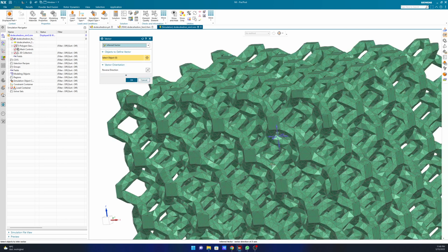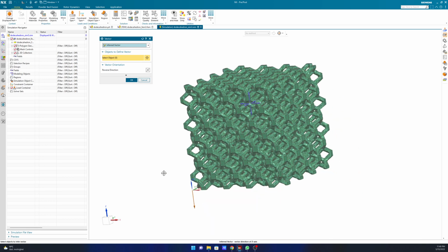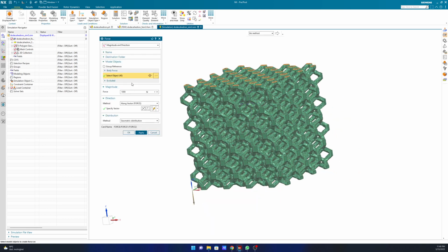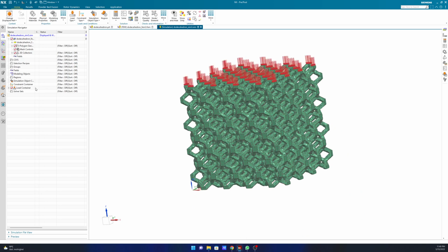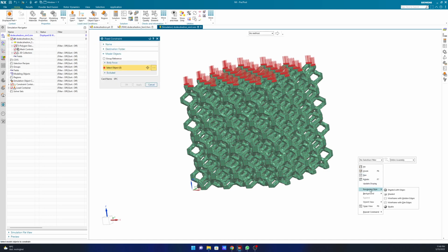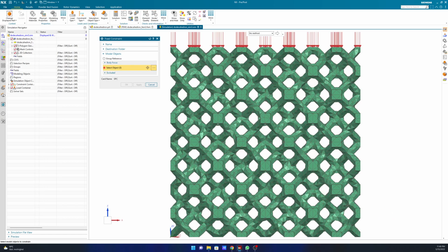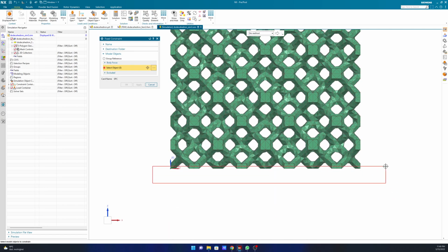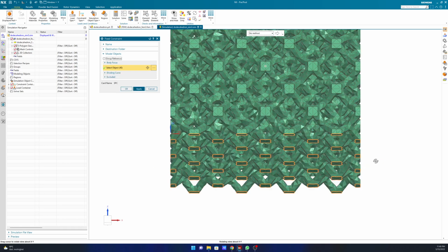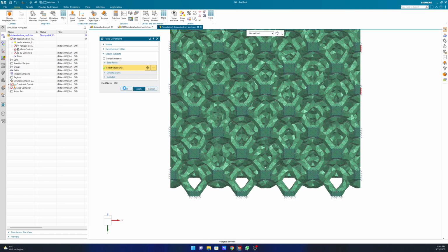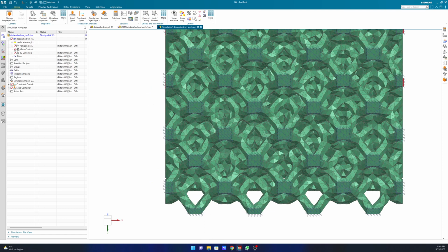Let's select that. Yep, it did. We have the direction, we have the load. We just click apply. There's a load. Then we'll have to put some constraints on it. Let's go with a fixed constraint on the bottom piece. Right click, go in the view, front, move it, select the bottom pieces. Guess that's good enough. Apply. We have our constraints there.